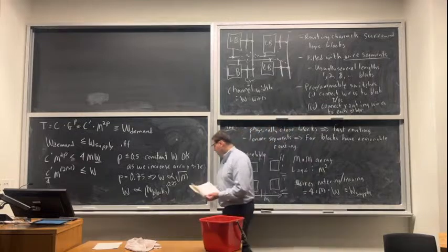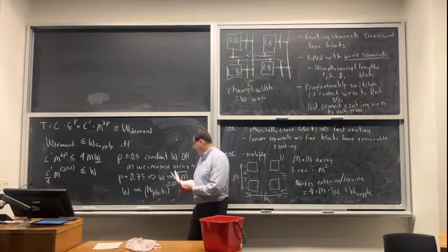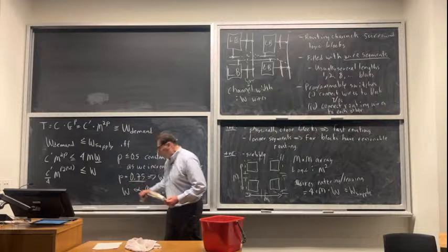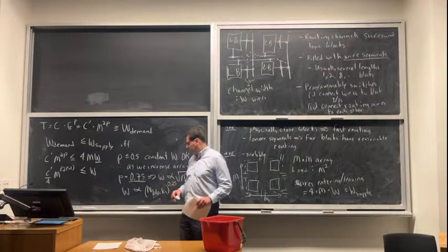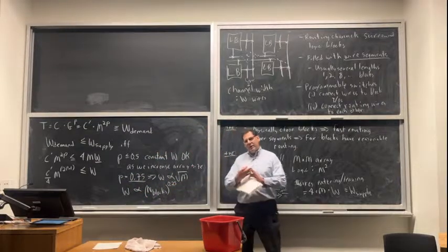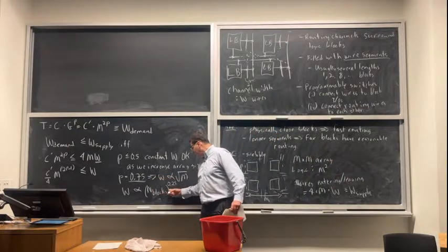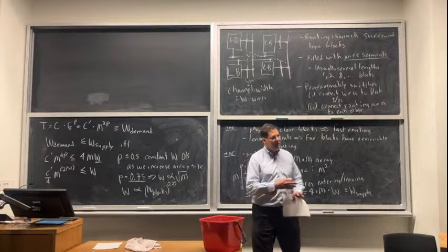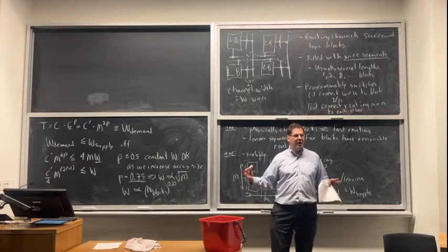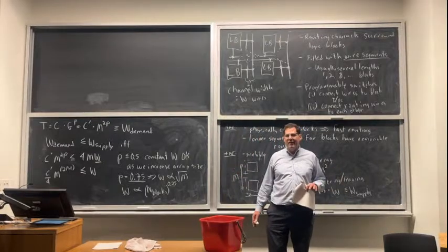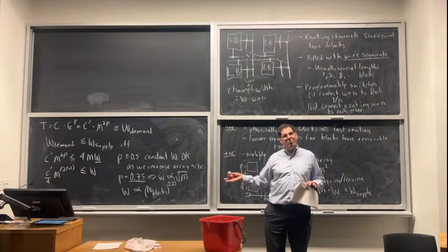So this is actually pretty good. This is actually a pretty difficult class of circuits, pretty poor locality. And it says, if you want to keep making bigger and bigger FPGAs and they can continue to route these circuits, you will have to increase your channel width, but actually quite slowly, only the 4th root of the size of the FPGA. So let's see, what does 4th root mean?